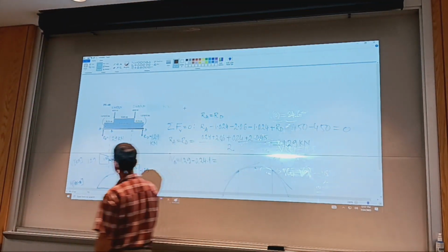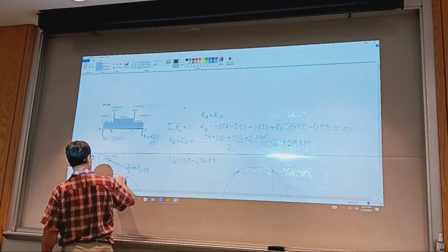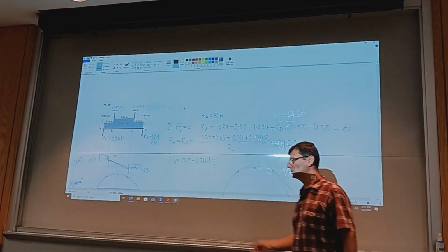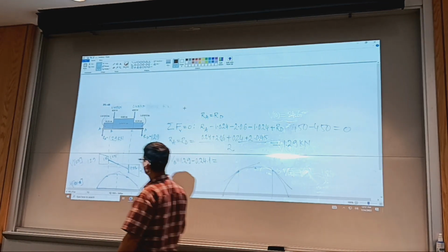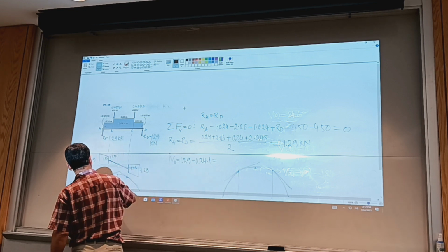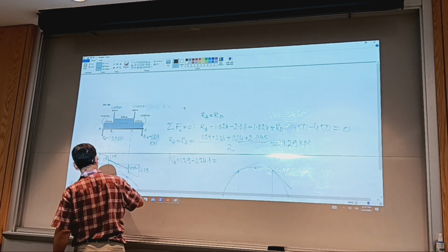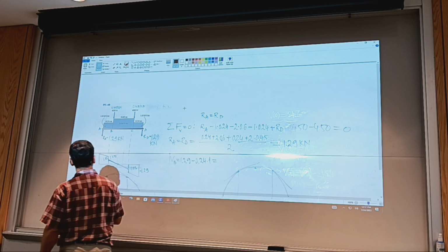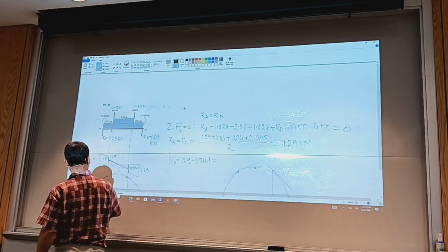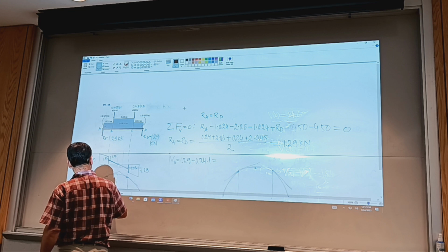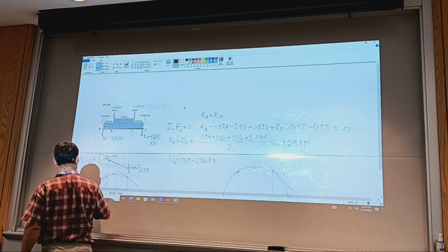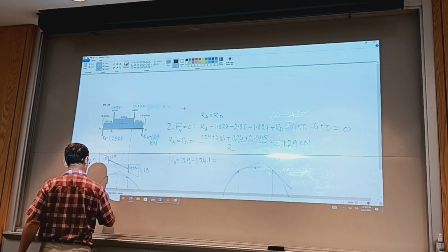It's zero order continuity, yes, but first order discontinuity, second order like this. If I want the maximum, or if I want the moments at the three locations, that's easy. It's going to be the area of a trapezoid. So the moment here is going to be (1.29 plus 1.05) times 0.24 over 2, area of a trapezoid.